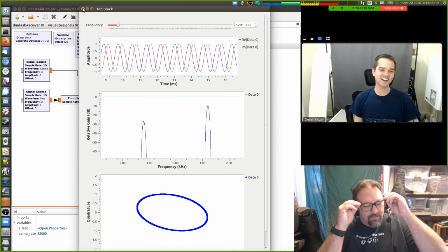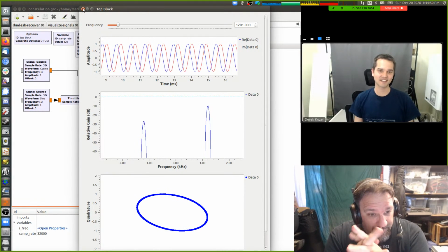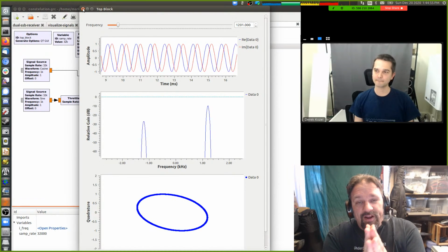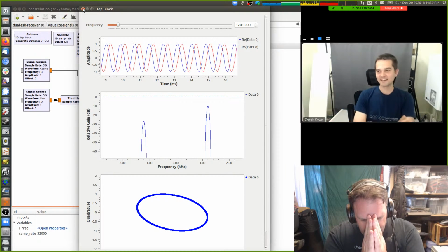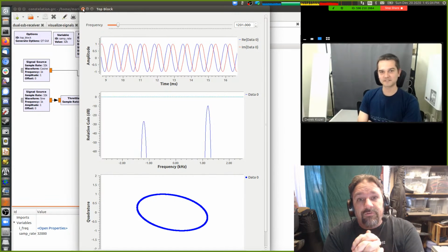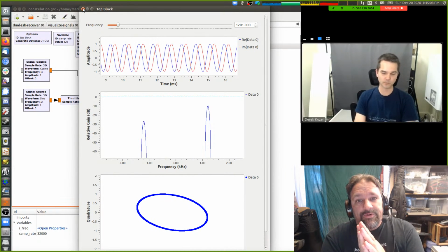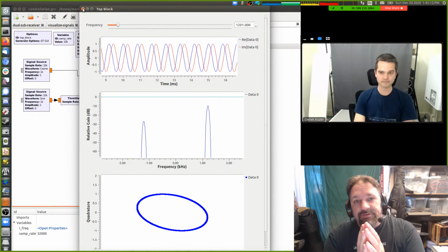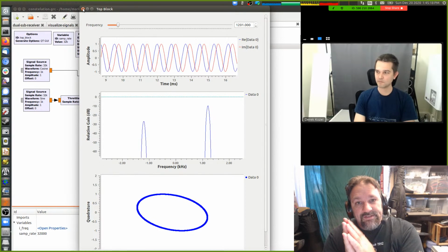All right, so, actually, describing the IQ imbalance might be the root of what I've been trying to wrap my brain around. When you have your signal represented as a float, and you've got a 1 kilohertz tone in that float, the timing of when you hit your zero crossings and your peaks and your valleys and whatever else is what represents the phase.